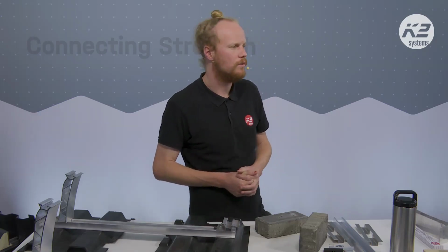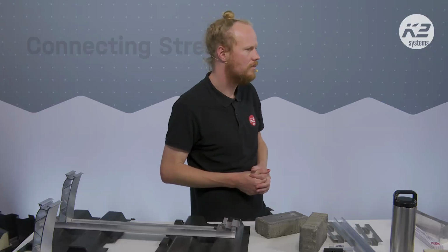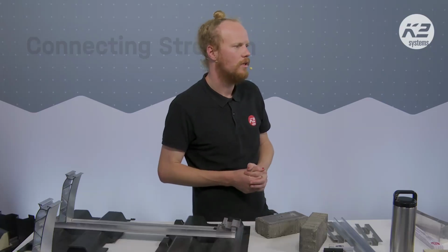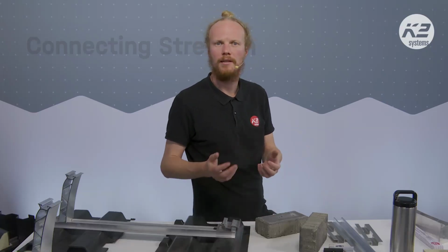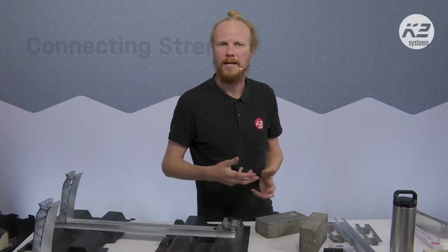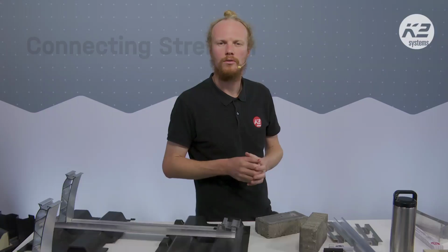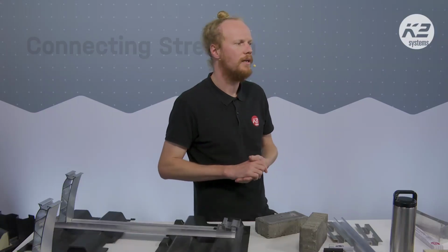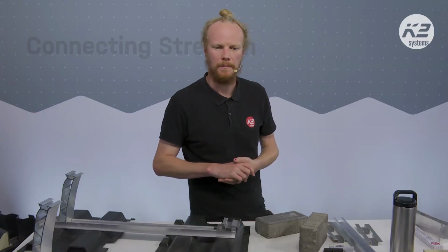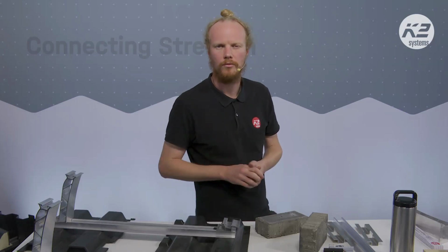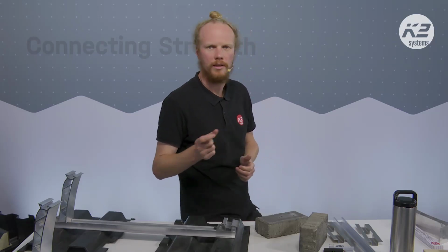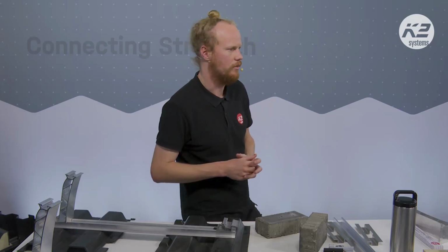So specifically to do with the ballasting values, because when you are going to add the stones specifically, you are still adding quite a bit of extra weight to the roof. And depending on how you deal with that, if it's a roof with a high load reserve, it could be something you really need to look into.